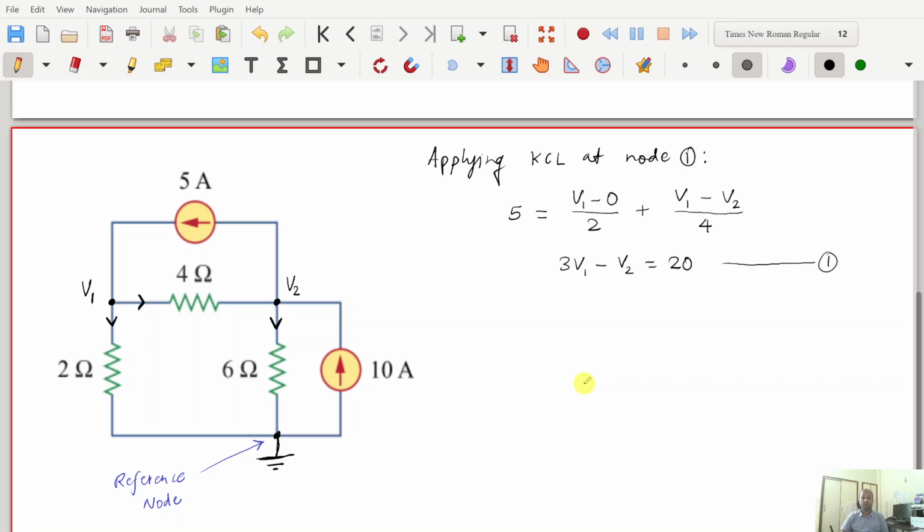As you can recall from the previous slide, in nodal analysis we make use of Kirchhoff's current law and Ohm's law. So if you see how we have written this particular equation, it is with the help of Kirchhoff's current law, and each of the terms on the right hand side represents Ohm's law. And the second important point is from equation number 1 itself. If you see, the unknown variables are in the form of node voltages. So whenever we solve a circuit using nodal analysis, the unknown parameters are going to be the node voltages themselves.